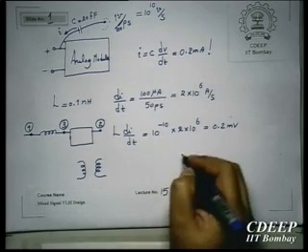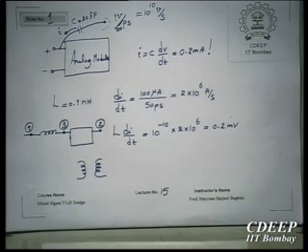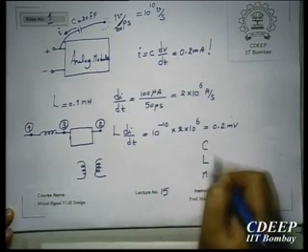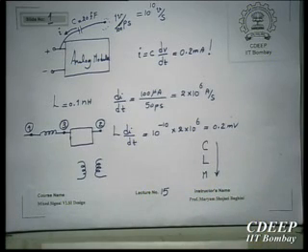I would say that if you want to look at the order of impact, first is C, then is L, then is M in CMOS technology. It's very difficult. Look at it in this way: if it is very difficult to make L, naturally it should be more difficult to make M, right? M is a function of L. L already is low, and M is not perfect. In transformers, because of the leakage of magnetic flux, mutual inductance is always not perfect.